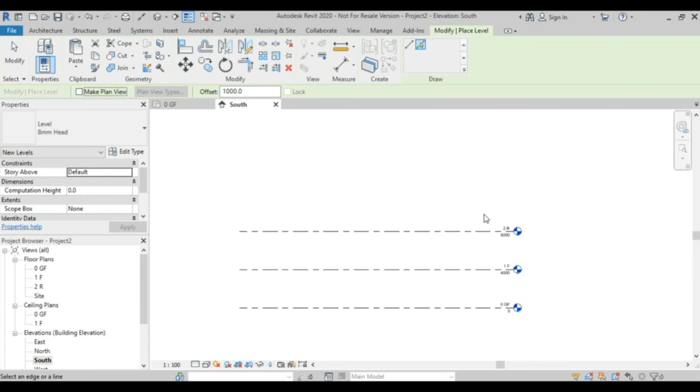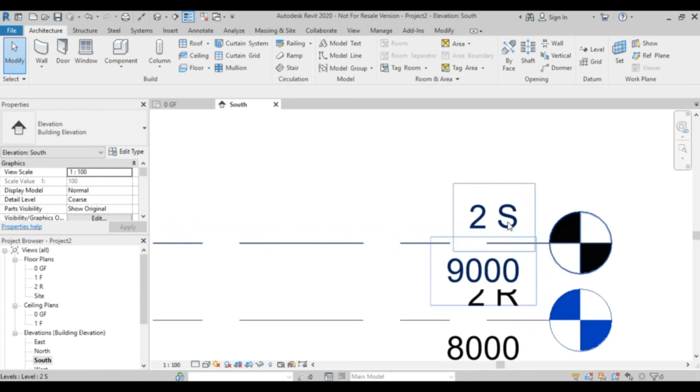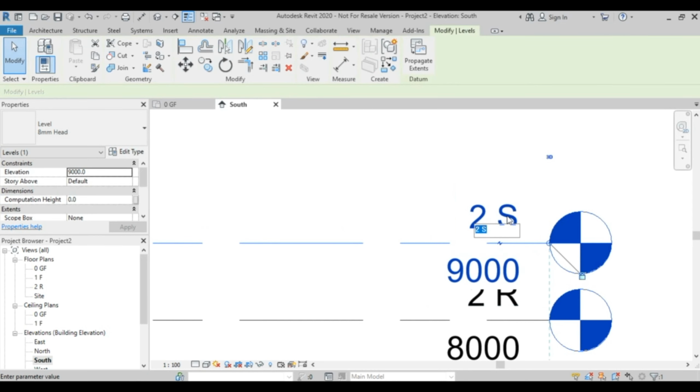If we need it later on, maybe we will create them once we need them, but for the moment I don't need them. I'll just hover over and click. It gave it a temporary name. We'll click again, and then we'll call it 4, and we'll use the P for the parapet.